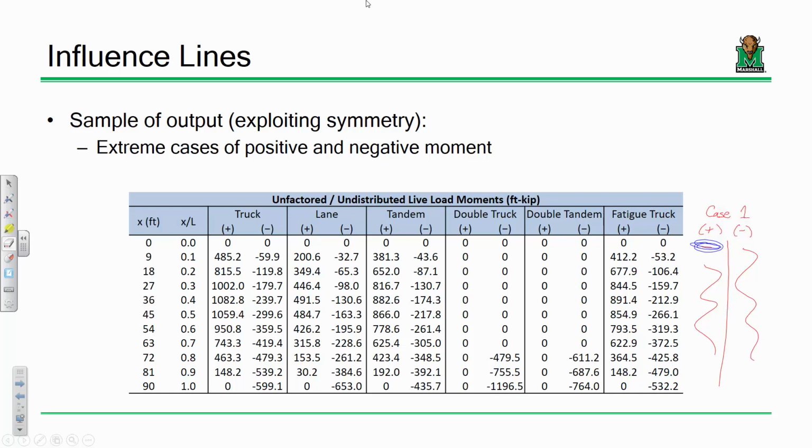And let me say this. If I had a really long, singly supported, say a 300-foot bridge, something really long, I'd probably do 20th points or something a little more specific just to make myself feel better. Because those are some serious spans. But for a regular run-of-the-mill 100, 120, 150-foot bridge, something like that, 10th points are fine.